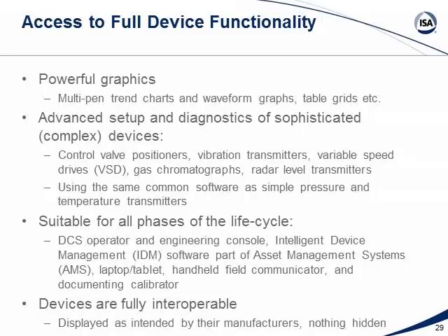So whether it's during the device setup, where you'll be using the core EDDL for device setup as well, but during other phases, FDI does provide some advanced functionality through additional plugins. We call these user interface plugins. They're DTM-like in some respects. This is the area where we sort of borrow some of that technology from the FDT group.